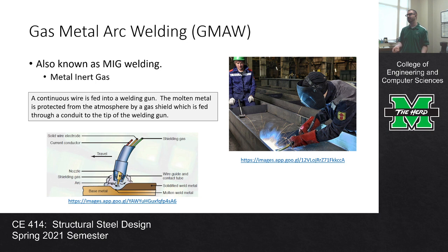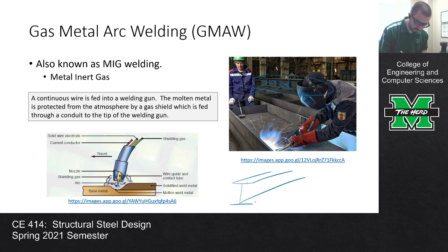The other thing that they can serve to do is to connect cross frames. For instance, if you look at this element here in the back, you can see that there are stiffener elements every so often, and there might be a cross frame that connects every so often. So here's your girder, you might have a plate here because there's a cross frame, and then a plate here and another cross frame, and those cross frames increase the girder's stiffness under bending, because in bending where the top's in compression, it wants to buckle, and that'll be something we talk about around April.